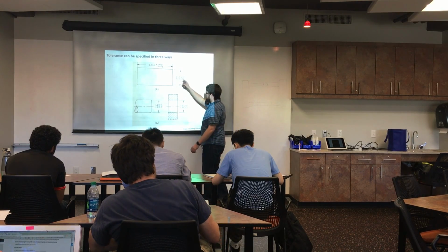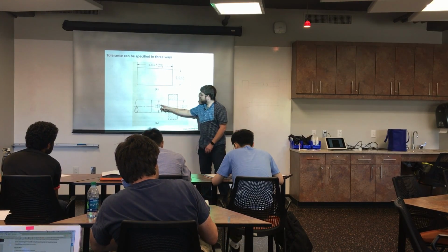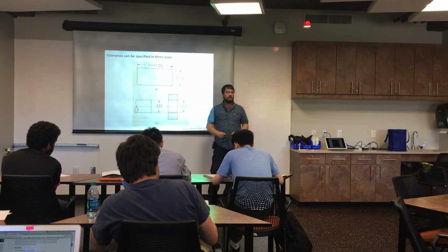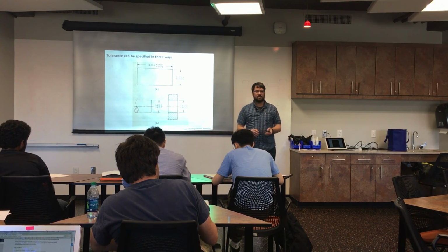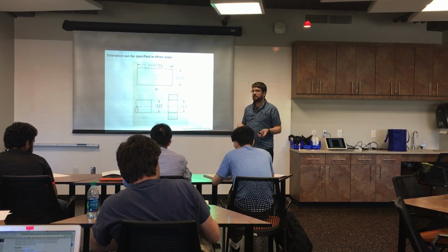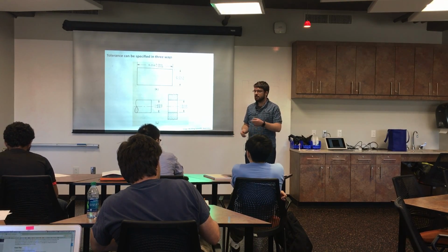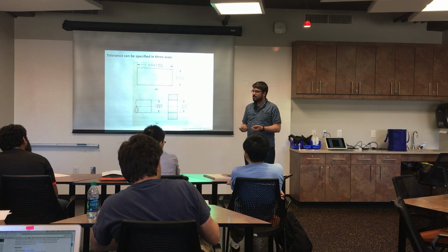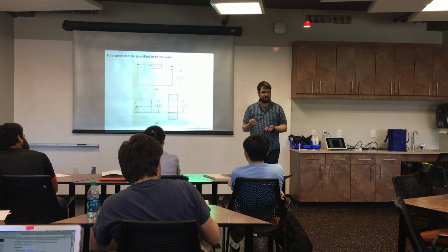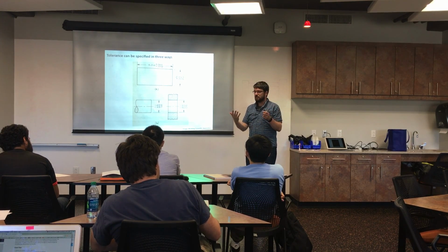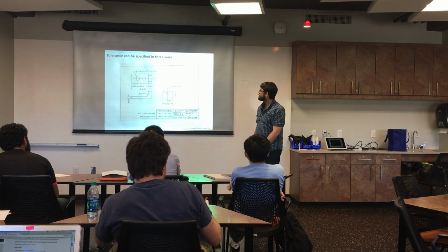Diameters, plus minus is pretty common. The other way is people specify the range that the part has to be in. And maybe it's an asymmetric range. Maybe it's minus 3 thou plus 1 thou or something like that. So you could just put the range in. And generally if you're making a lot of these, there will be what's called a go, no-go tester that has the minimum and the maximum size, and you try to put the part in and make sure that it fits in the range.